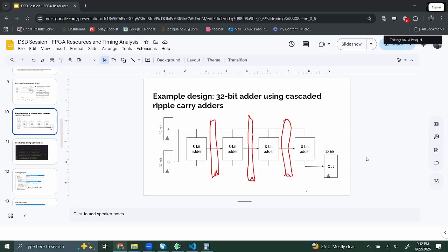Pipelining is so because in a given cycle, if we only process one input, in the first cycle only this part will be used. In the second cycle only this part, and like that. But because the other parts of the circuit are unused, and they are also isolated by these registers, we can start processing the next input before the first one has completed.